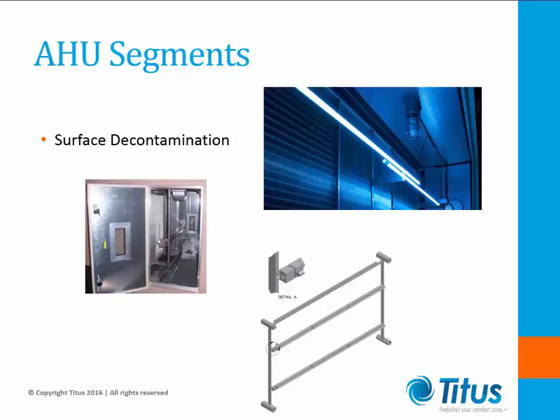The kill rate increases dramatically with this option since exposure time is unlimited. This is important since mold and other spore-sized organisms have a much higher kill threshold than bacteria or viral contaminants and require a longer exposure time to kill them. Applying this option to the AHU doesn't warrant much space claim and typically can be configured in the cooling coil segments.